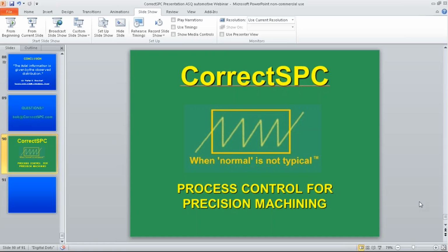As far as your sampling, if you measure one diameter out of an infinite number of diameters, its significance is 1 out of infinity, which is nearly 0. So that's why when you do the high and low, you've actually captured all the values, which is extremely significant. You've gone from 1 out of infinity to every value. So that's why it's a far more powerful tool.